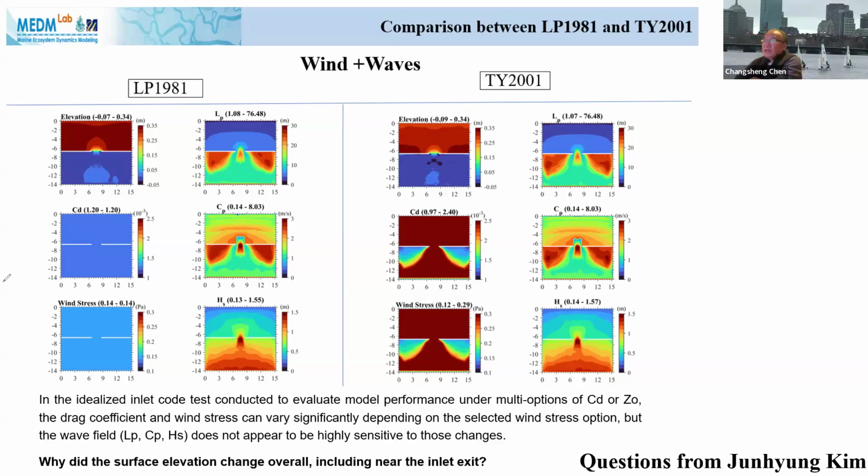Also, we can include the CORE 3.1 program for the wind stress calculation. It also recalculates the long wave radiation instead of the older coding. Now I think we have CORE 4.0, which Dr. Lee has added into the FVCOM code. So you can use this method, but I think the CORE program is a pretty good method because it has been tested over a long 10 years for heat budget calculation.